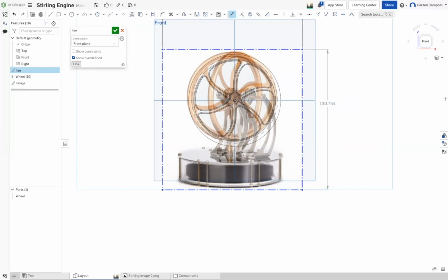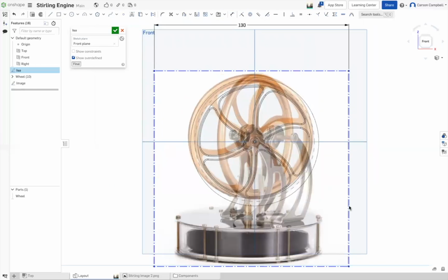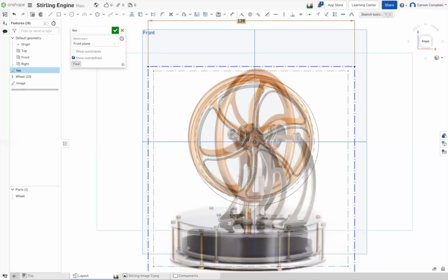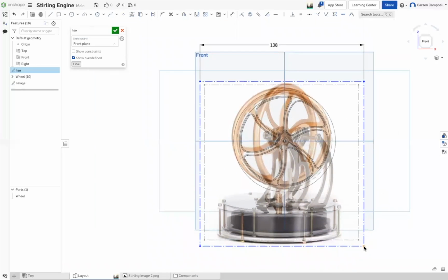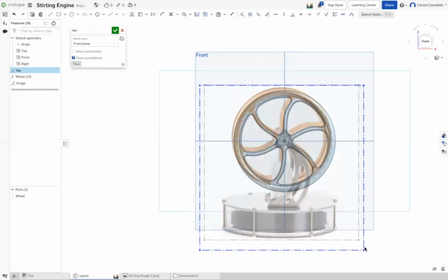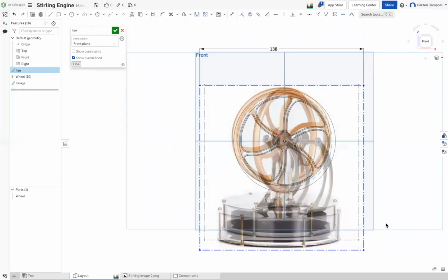Click on it. It's giving you that it's a driven dimension. Yeah, driven. So delete that. Hit the F key on your keyboard. There you go. You see the dimension that's already up there? Change that to 135 or 138. Now position it. Exit. Say okay.